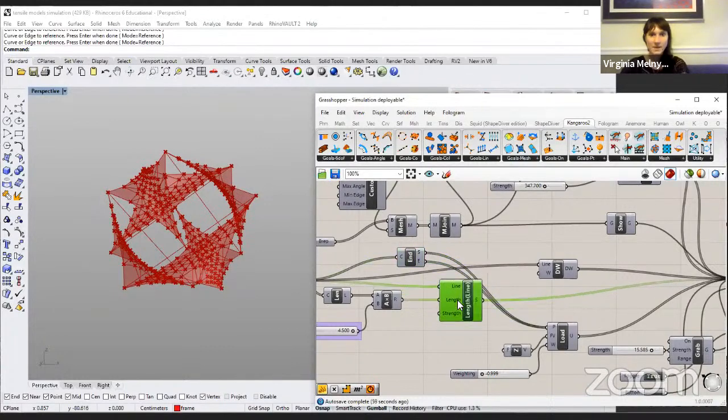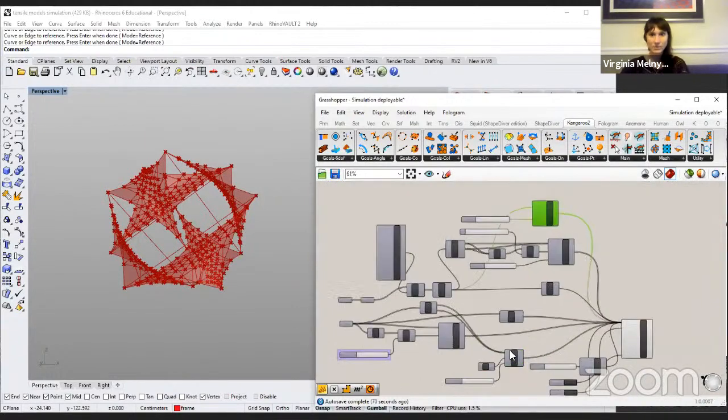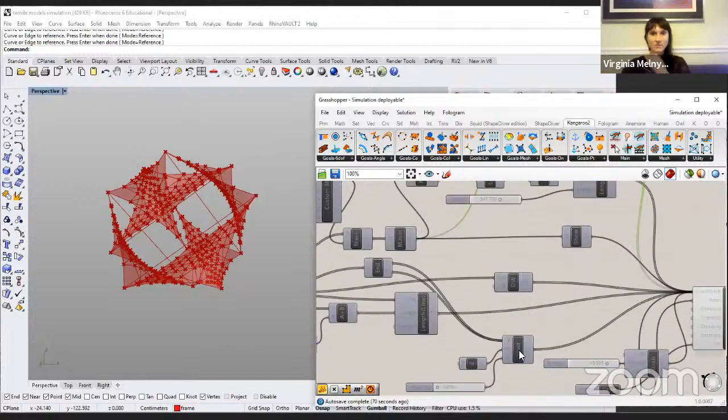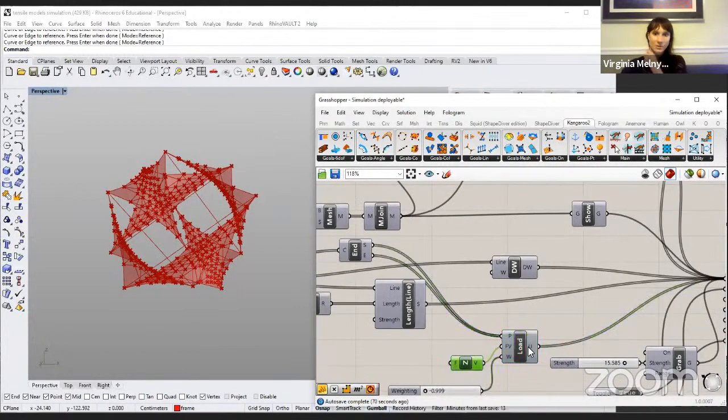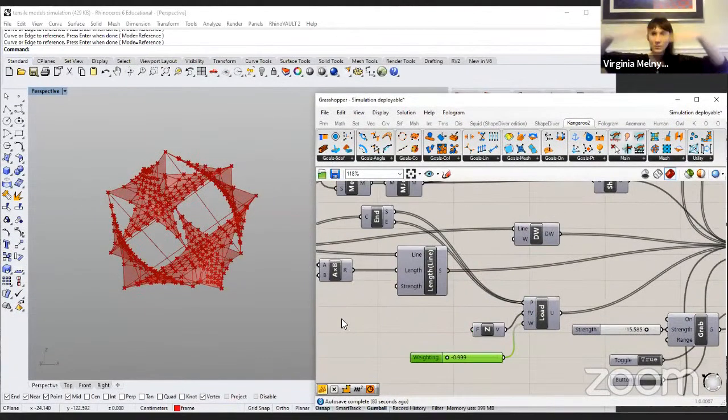So from the stick, we also need to get the starts and ends to add a point load to those as well. So to those points, we add another gravity load because we applied the gravity load to the fabric, but we also do need to apply a gravity Z direction load to the sticks. So this also is just a negative load to add weight to the sticks, which would weigh themselves down.